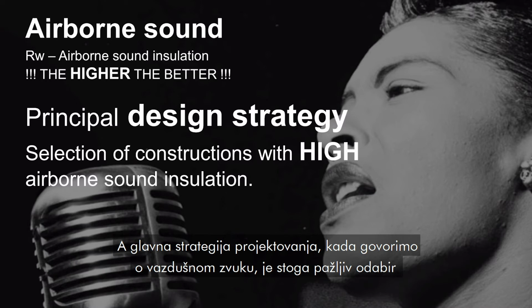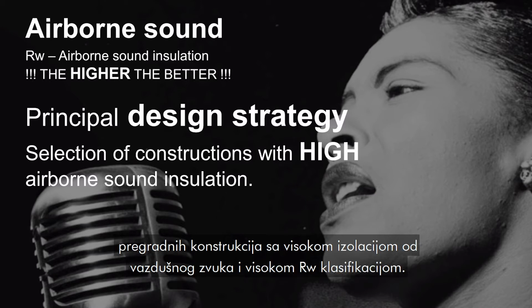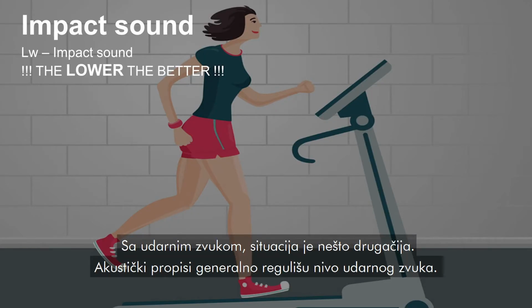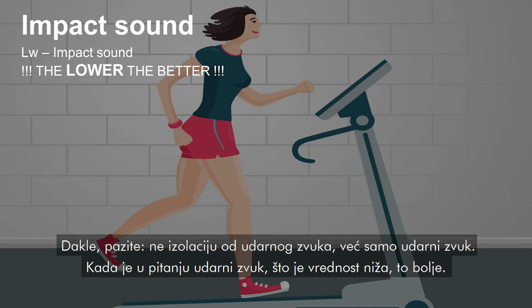And the principal design strategy when we talk about the airborne sound is the careful selection of constructions which have high airborne sound insulation. With the impact sound, the situation is slightly different. Acoustic regulations will generally regulate the level of the impact sound. So just be careful, not impact sound insulation, but just impact sound. And for this impact sound, the lower the value, the better it is.